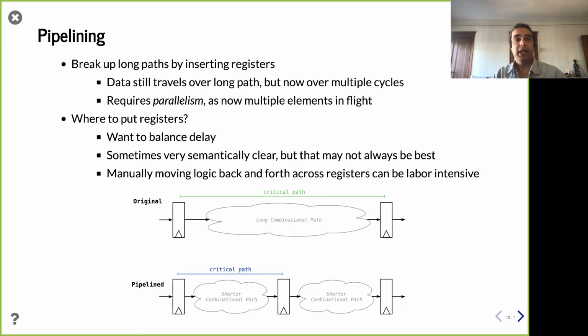We know that advanced processors can look at the dependencies and dynamically reorder instructions, doing them out of order, but the original semantics of the program was very much sequential. As a result, there are a lot of dependencies between different cycles, and so that's arguably the hardest thing to pipeline, right? And you learn about that. You learn, oh my gosh, when you pipeline CPUs, all these challenges about various hazards and various hazard mitigation schemes and all these other challenges.